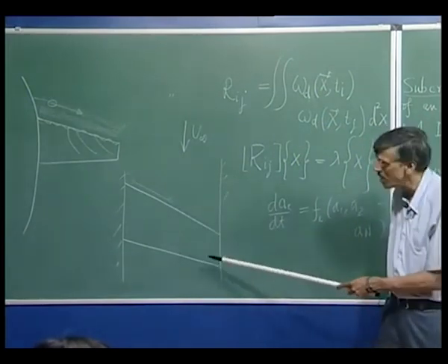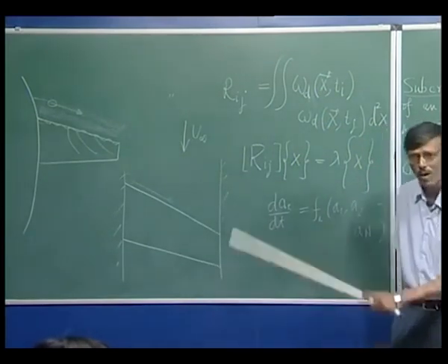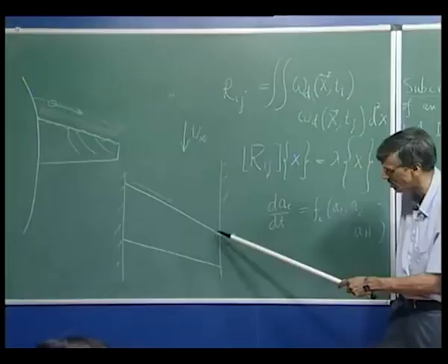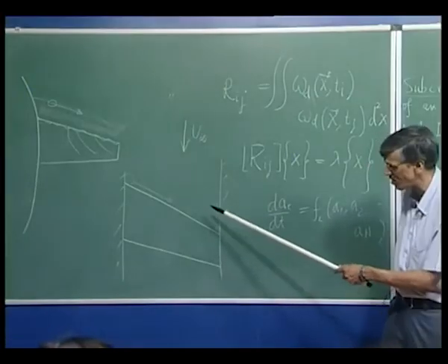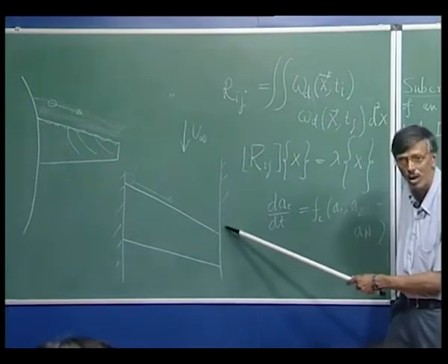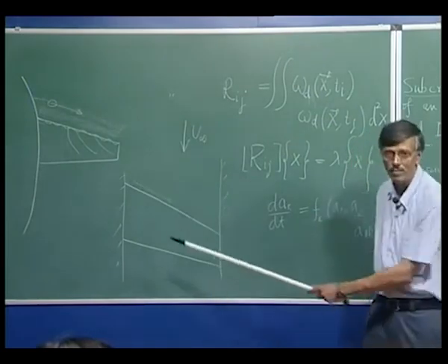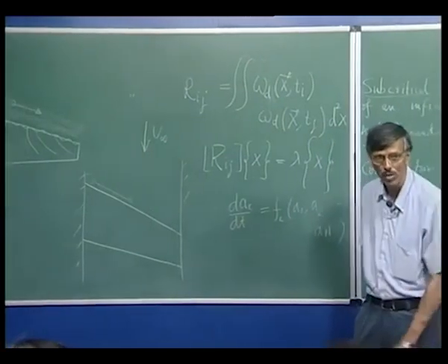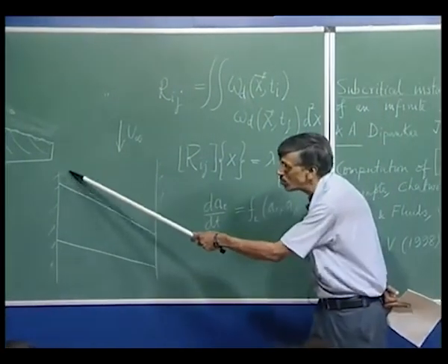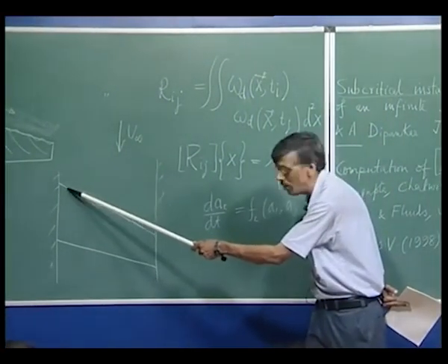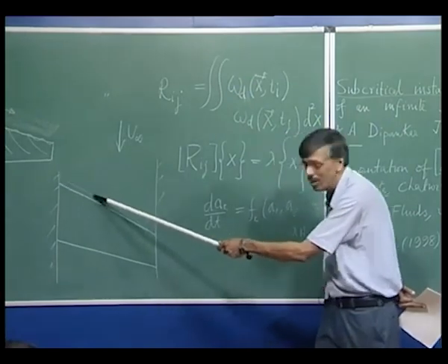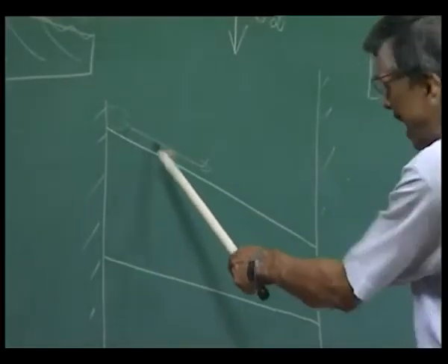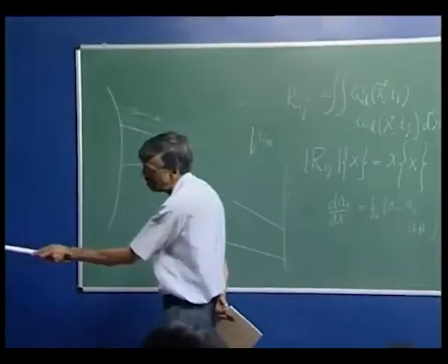So, that is why these experiments are very trustworthy and reliable, simply because the vortical structure that is created on the other wall will not propagate against the sweep. Instead, the vortical structure that is created here will naturally move along, right. So, that is your attachment line plane, the way we have shown here.